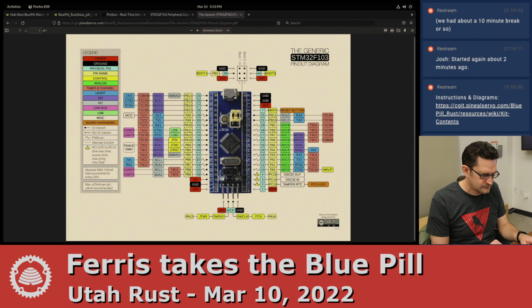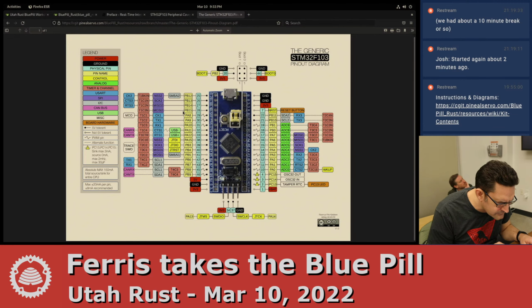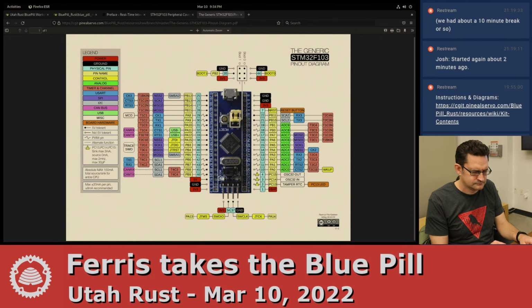Yep. So which one was the clock again? You can tell from right here, SCL1. Or no, we said 10 and 11, right? So I think we're over here. Yeah. So those are the two, pins PB10 and PB11, that need to be connected to the display.